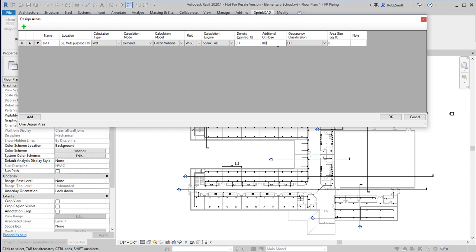And you'll find the same basic requirements in all of the different codes that are referenced and processed according to the software. Its occupancy classification is light hazard, and I was told that I have a 900 square foot remote area minimum. And then I'll just put in a note here, demo calculation, just in case anybody gets a hold of my calculations and tries to submit them as their own. Wouldn't want that.